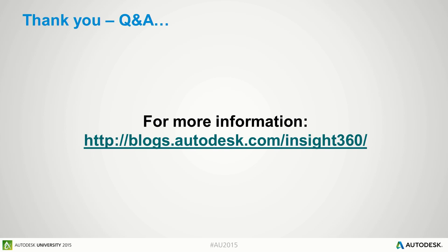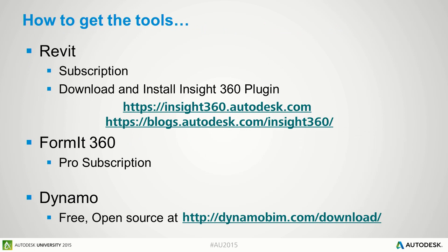The last slide said Revit was a subscription. Insight 360 has a number of tools that are each slightly different. The energy analysis goes through Green Building Studio, which you get with a Revit subscription. The solar analysis will work for anyone; you don't need a subscription. The lighting analysis has a free level, and then more detailed analyses require cloud credits. Each one's a little bit different. And then there's a loads analysis that also works off the energy analysis in EnergyPlus, so that requires a subscription also.